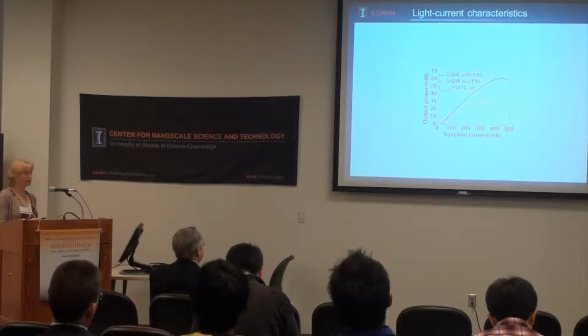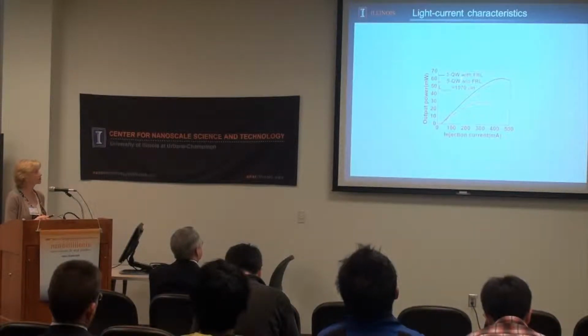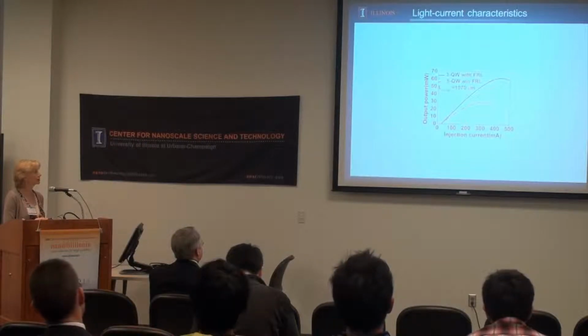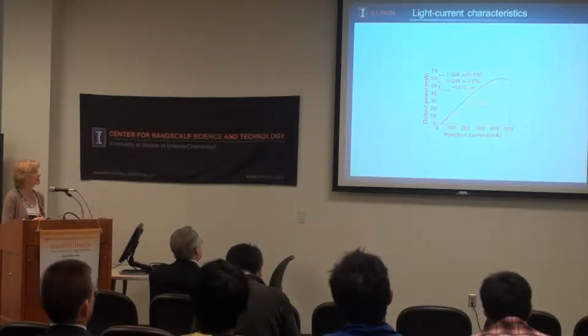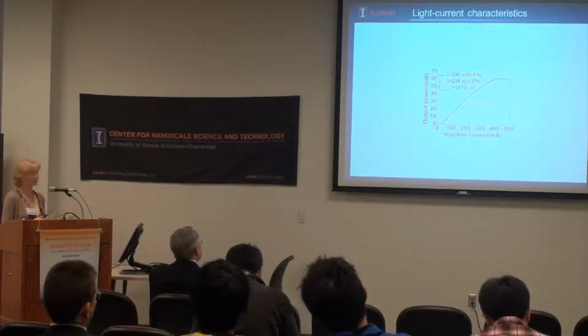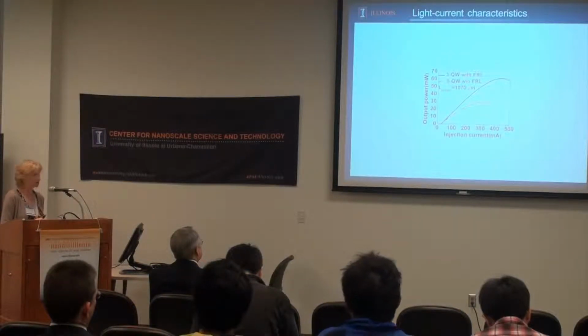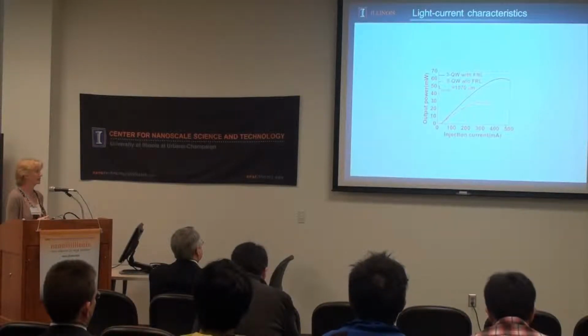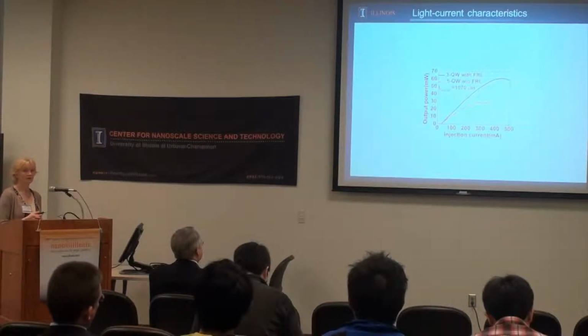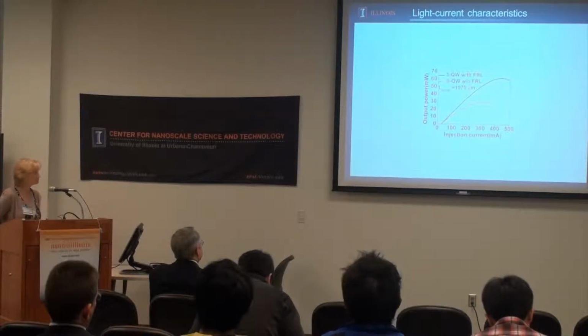Now when we compare the performance of the new structure, the 3 quantum well structure, with the 5 quantum well structure, just looking at the CW output power as a function of injection current, you can see we get powers that are at least twice as much coming out before it starts to roll over. This rollover is due to heating, which is caused by the light being reabsorbed in the cavity, and non-radiative recombination, which should be small, but it's mainly the reabsorption of light. And you can see that reducing the overlap with the P cladding layer has helped that immensely.